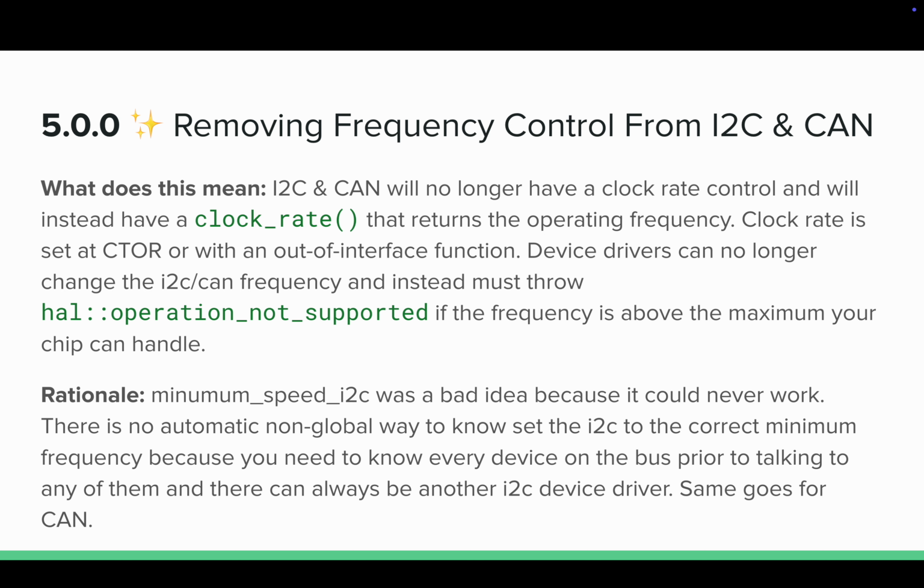So one of the ideas I have is that I2C objects, I might frame them a little differently. I'm still coming up with the concept of what a device manager will look like for libhal, and I think it'll be different for each type of interface. But the idea would be that you'd have some I2C class that does not implement the I2C interface, but it allows you to control frequency and allows you to do other things. Then you're able to acquire, or borrow, or steal, or whatever. You're able to pull out an I2C from it. And what that does is it tells the I2C device manager that, hey, there is a shareable I2C that exists currently.